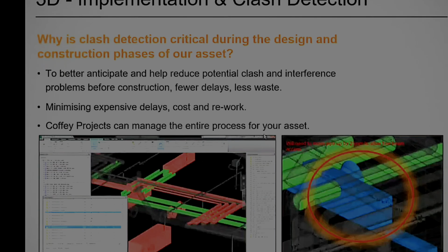We followed the design drawings, right? We followed the design consultant's drawing. But when we actually virtually constructed, we see a lot of clashes, a lot of issues happening. Pipe is penetrating through a wall, pipe is penetrating through a column. There is no soffit given to cover mechanical services. So there can be different types of issues which you see virtually when you combine all of the models.